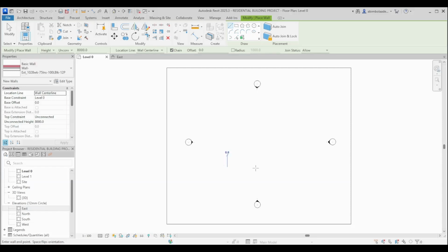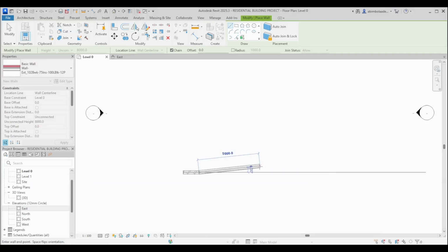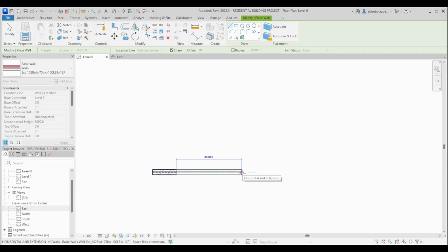For my sketch, I'm just going to left click and type. You can type in the distance you want. I'm going to type 1280 first. Whatever distance you have from your sketch, just feel free to type it in. You can zoom in by rolling the scroll wheel, as in my previous lesson. You can also type in the next distance if you know. So I'm going to go 44690. I'm going to press enter.